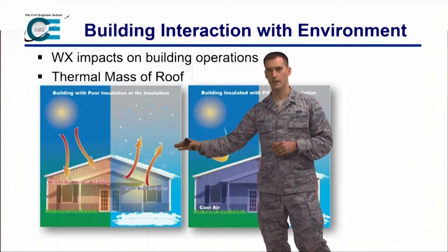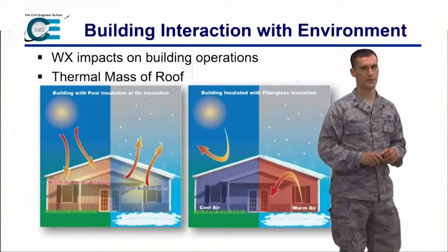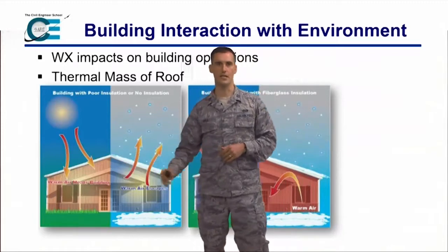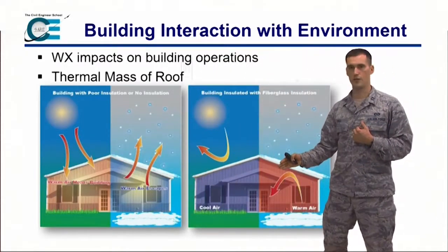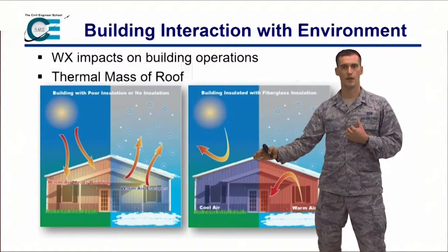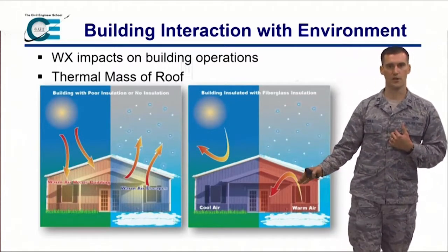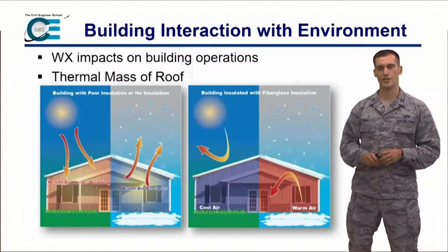In the winter, in the nighttime, we're losing energy out of our facility. All of these arrows, that heat transfer, is what I'm primarily concerned with as a mechanical engineer, and our goal is to limit that. So we do cool roofs, reflective roofs, in order to limit that heat gain, and we try to bulk up our insulation in order to keep that energy inside.